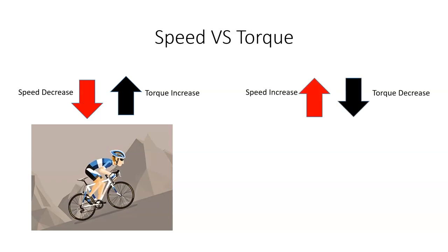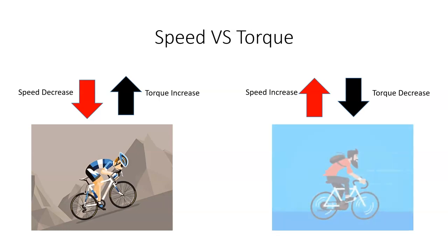Now, what about when you're trying to increase the speed? So you have a speed increase where you're going to see a decrease in torque. And again, if you remember and think about the radii of the different gears, or the number of teeth of the gear, and that key equation, velocity is equal to R times omega, that also rings true, right?